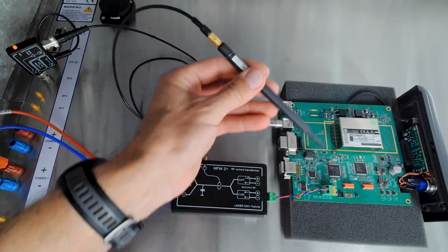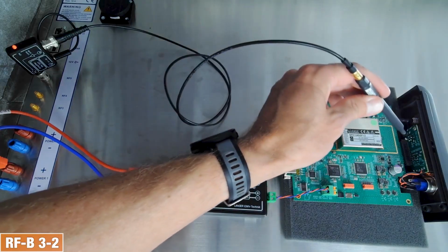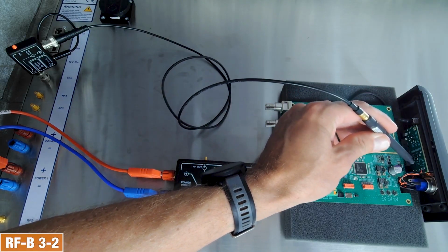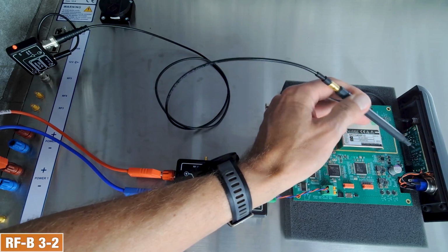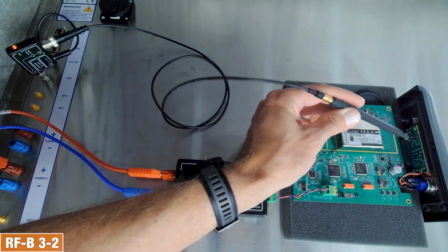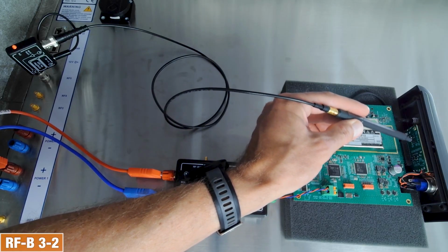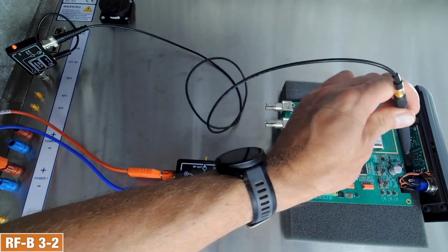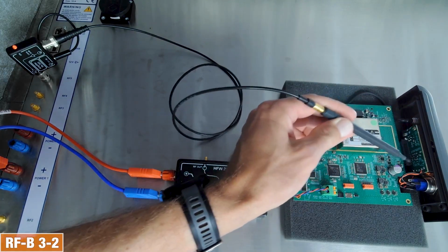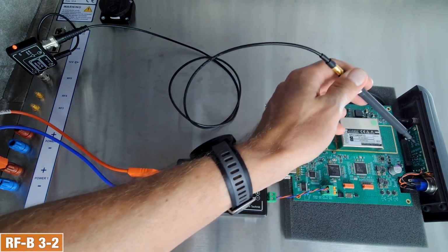This is then a smaller magnetic field probe. And then you can go deeper into your layout or deeper into the PCB. Because with the smaller probes you have a better resolution, and then you can find the traces or the pins here in the connector which are creating these disturbances.